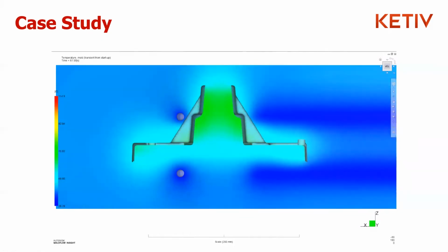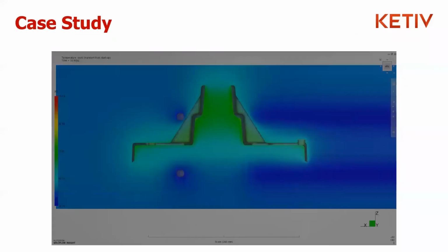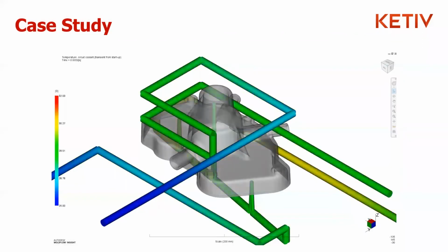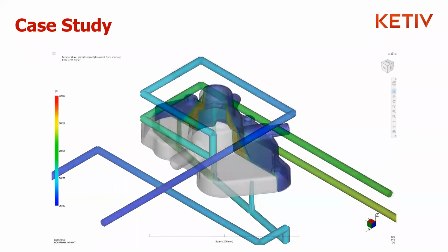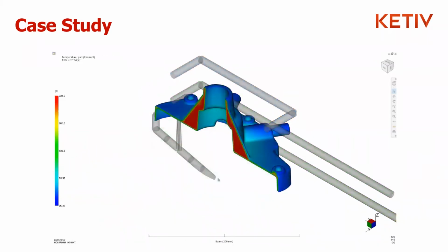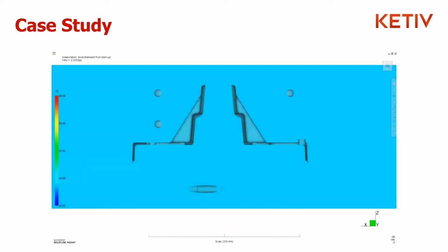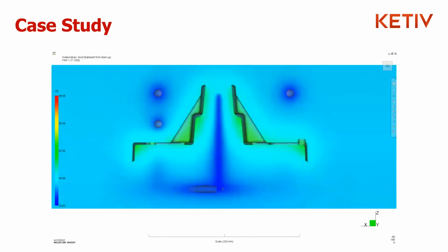So let's say it gets slightly more complex and you start to use a more complex cooling system, right? So this is more realistic, it's more machined. Essentially, this is like a conformal cooling channel system, but it is still limited by channels actually being machined in, right? So even though this is slightly better than the oversimplified version in the previous slide, this still is not ideal. We still have some irregularities and non-uniformity in the cooling.